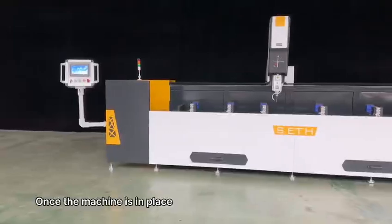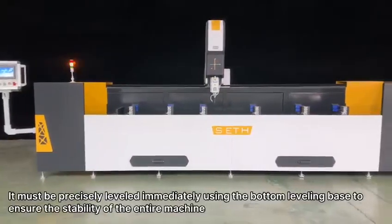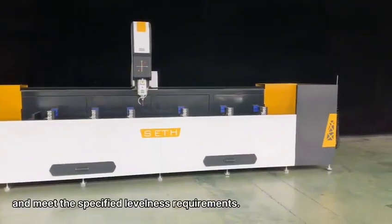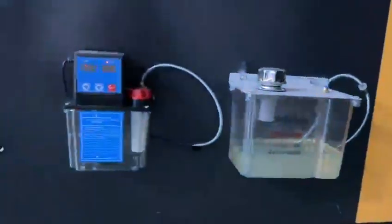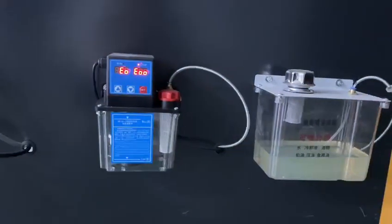Once the machine is in place, it must be precisely leveled immediately, using the bottom leveling base to ensure the stability of the entire machine and meet the specified levelness requirements. Fill the water tank with the machine-specific cutting fluid until the specified level is reached. Add its special lubricating oil to the automatic oil pump.